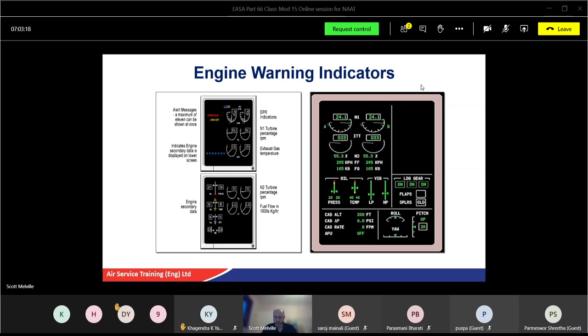On which type of engine, fixed turbine or free turbine, would you find dual lever controls? Free turbine. Free turbine, yeah. And the same sort of engine on a power lever, when you go into the beta range, what is the angle you can change the blade pitch from? Positive 20 and negative 20. Good.